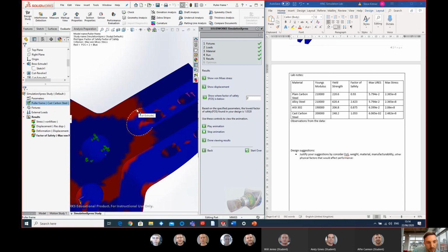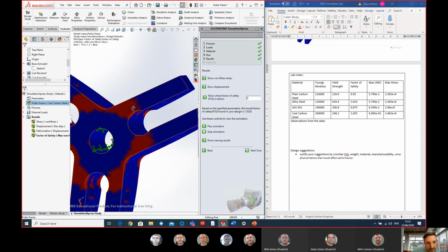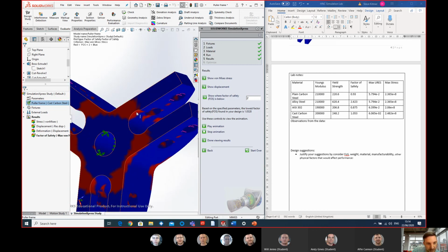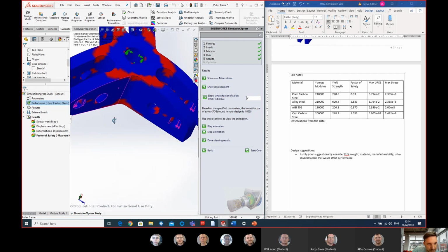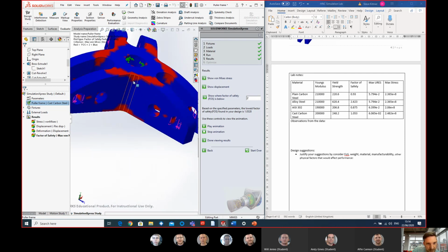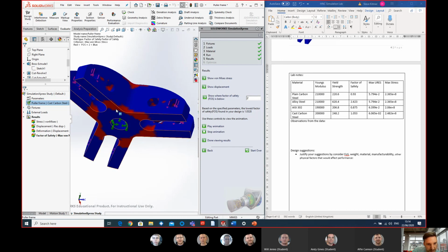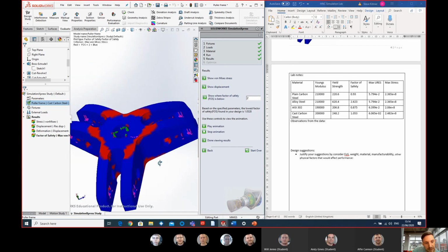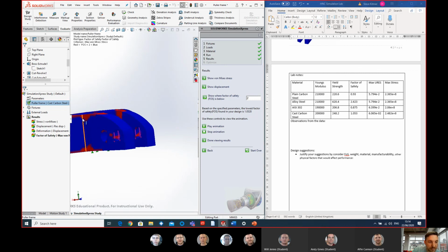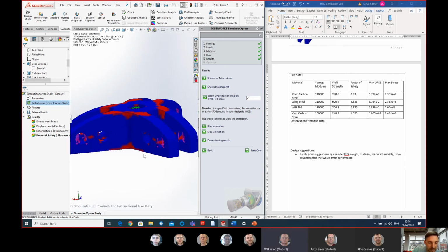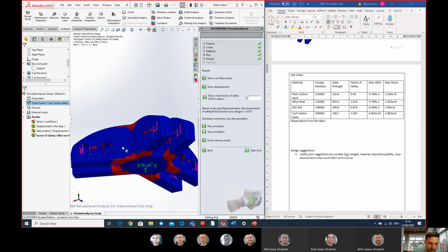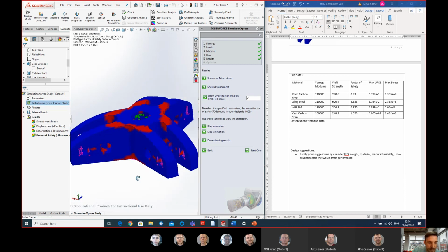So is there a way that you could get around or make that little bit a bit stronger? That's where it's always going to break. Just across the top of here as well, maybe, but I think that bottom point there is where most of the stress is coming in. So again, if this was me making this part, I'd be trying to make some decisions on how I could improve that. Can I move that stress a little bit further away?